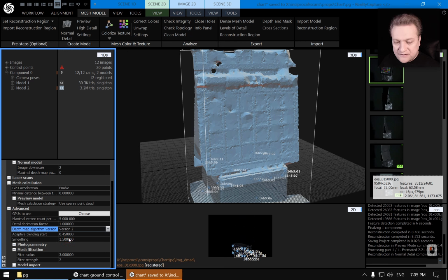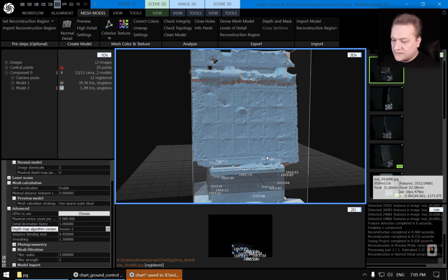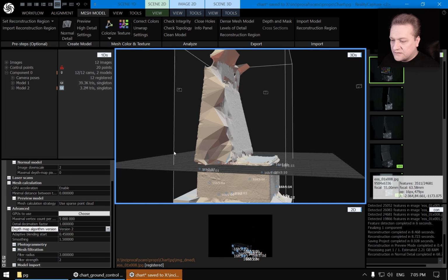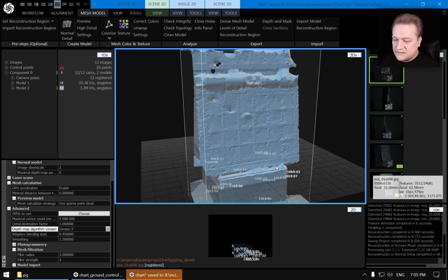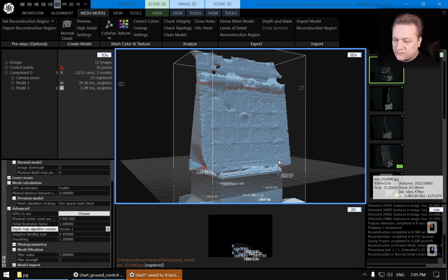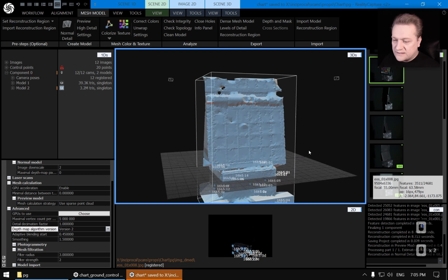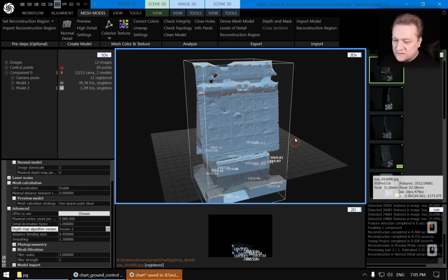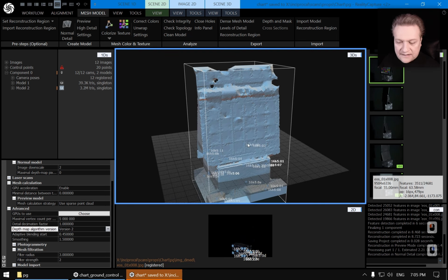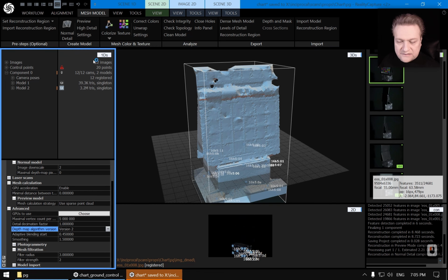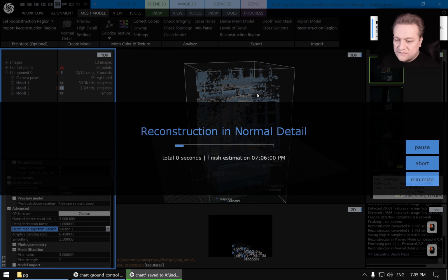It might be 2 in later versions of Reality Capture, but the cool thing that you see here is that using those ground control points, the mesh is nicely aligned and oriented, so we don't need to do anything extra there. Anyhow, let's try this algorithm number 2 for depth reconstruction, and let's pick the model that we like the most out of the two.